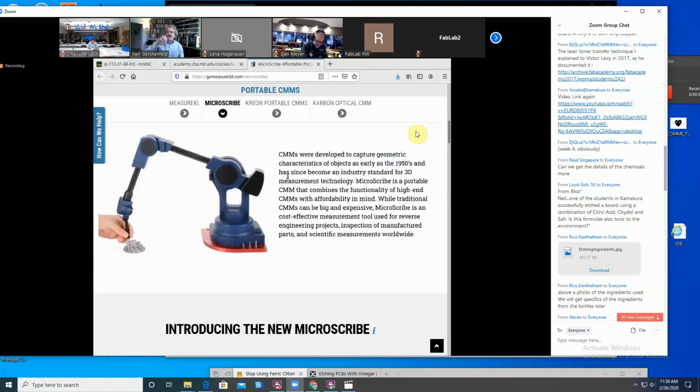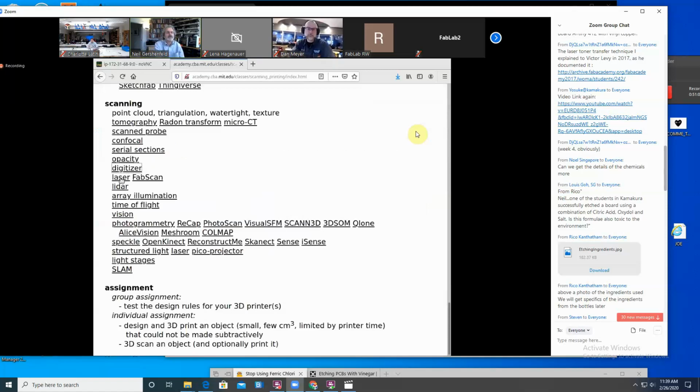And then rather than digitizing the whole thing, you don't need to digitize everything. What you want to do is digitize the important features. Where are the boundaries and where are the corners? With these arms, you have a button for your finger or a foot pedal, and you touch it to points, and it measures where you are. And so you add value, because by choosing where you digitize, you're getting a very clean scan, because you're picking what points to measure. So those are digitizers.